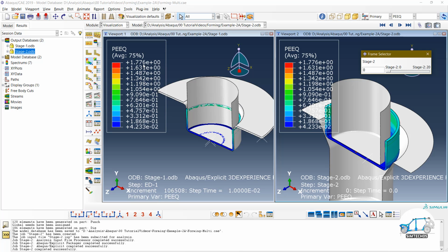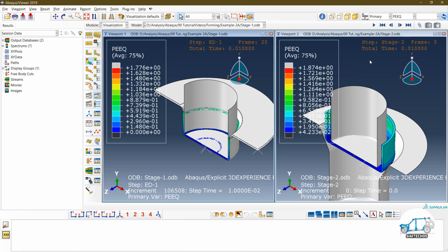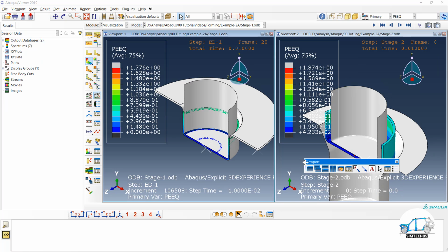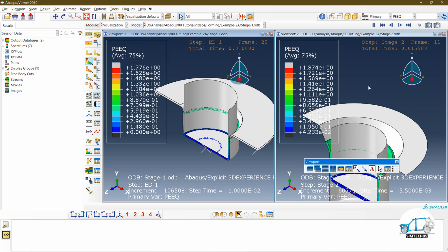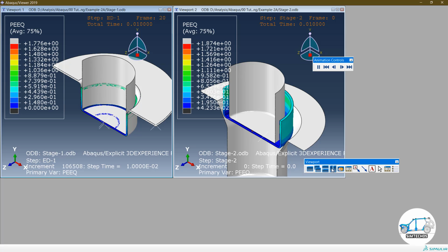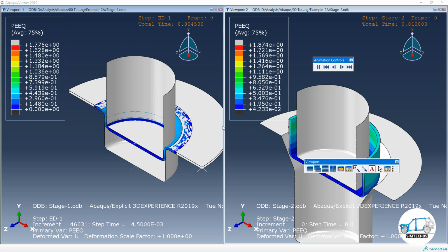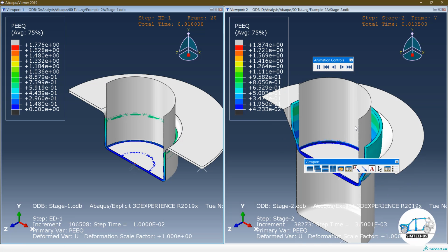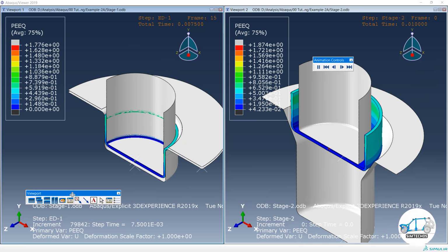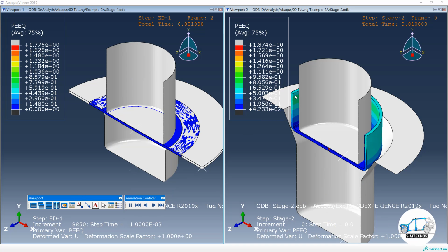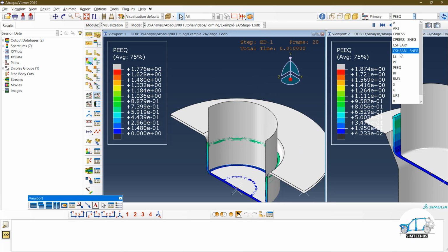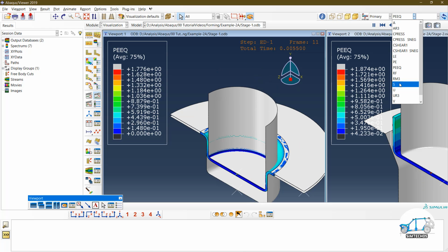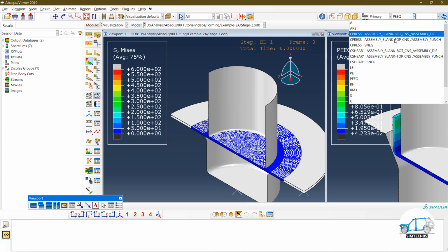So that's all for this video tutorial. This technique not only helps in multi-stage forming simulation, it helps a lot when you have such a combination of explicit and general static type of simulation. Say I want to perform a coupled thermal structure simulation with the explicit step, then I want to see the cooling effect. So performing the cooling analysis for 300 seconds or maybe 1 hour, maybe more than 1 hour, performing such a cooling simulation in the explicit step is near to impossible.